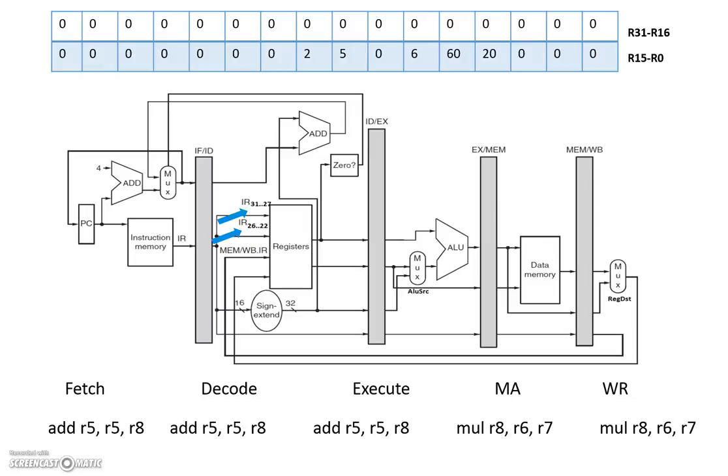This operation will happen again, stalling will happen again till the time when the write back register has the same instruction as that of the fetch stage, which will happen at this clock edge, and we will have value 10 in the register file, and previous instructions will be passed on to the later stages.